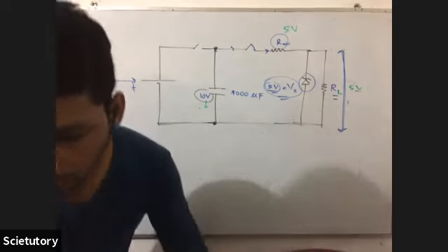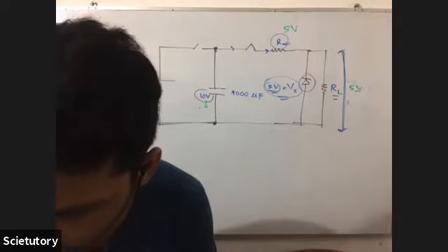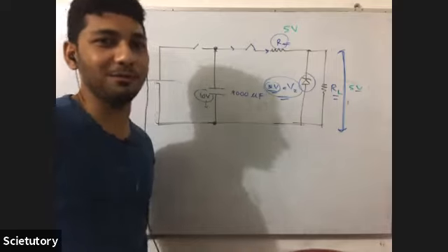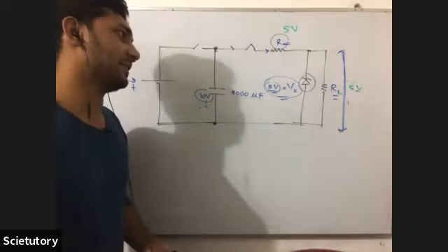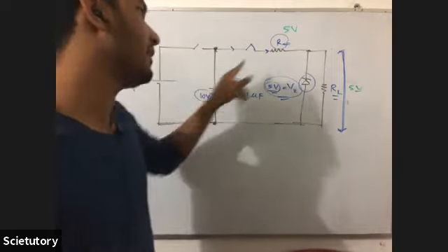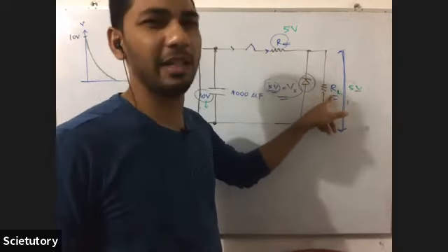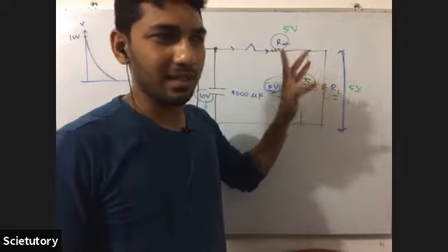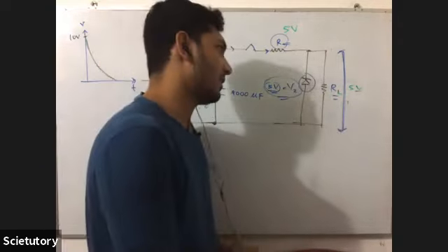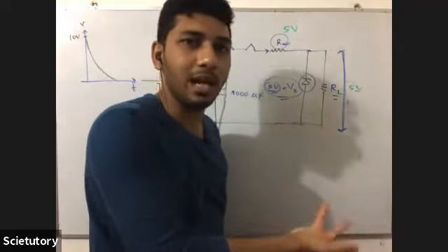So first, voltage across RL will be 5 volt as long as the capacitor voltage is adequately above 5 volts. Adequately above. What do you think? So for example, if it is 5, when you distribute the voltage between these two, this is definitely not 5, less than 5. But they are telling that adequately higher than 5. So there is a chance that the voltage difference across this to be higher than 5 volt, no?